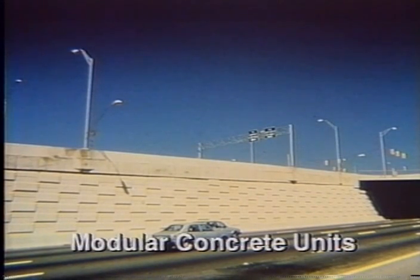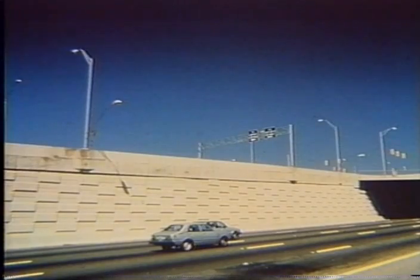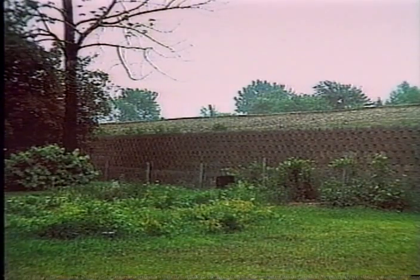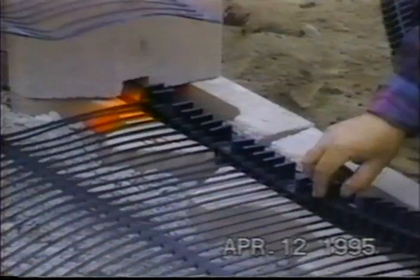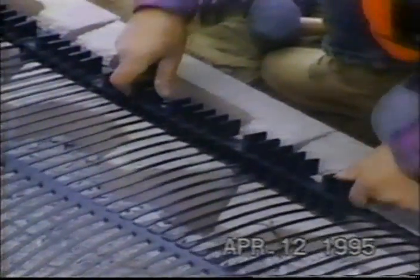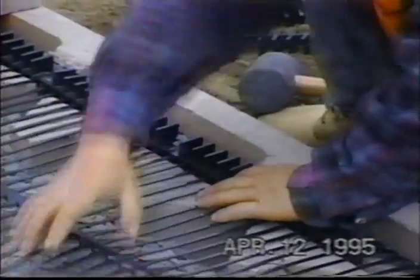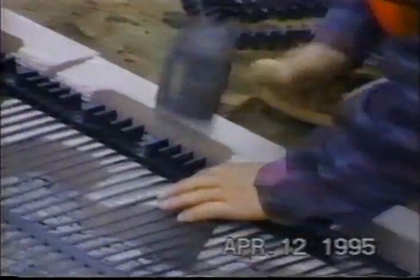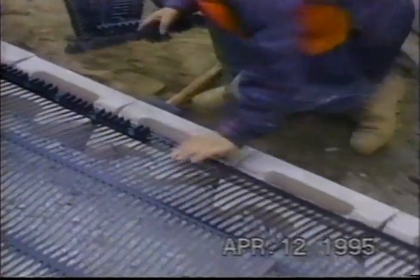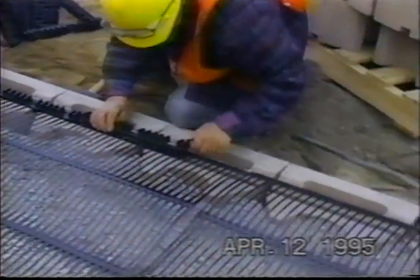Modular concrete units, MCUs, are now by far the most popular geosynthetic wall facings. They are relatively easy to construct and offer a range of aesthetically pleasing finishes. Units are connected one above the other with pins or lips, or in this case with geosynthetic connectors. The strength of the connection must be addressed in design and can control the maximum tensile load in a given layer of reinforcement.